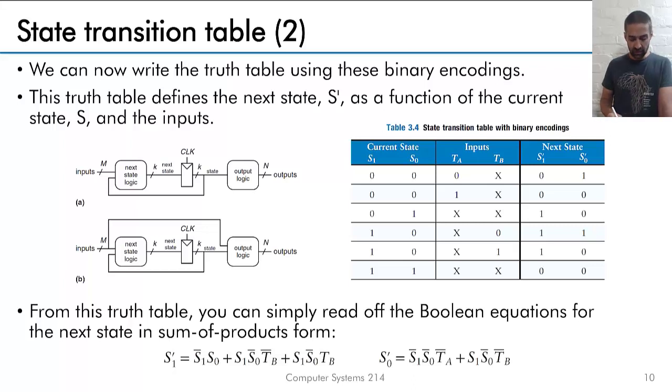And just to refresh your memory, this is the state machine. We have next state logic, output logic, and the memory that remembers what the present state or the current state is. Now we're going to develop this next state logic using that state transition table. So we use, as I said, the codes for S0, S1, S2, and S3. Exactly what we had on the previous table, we've just written down using the codes.